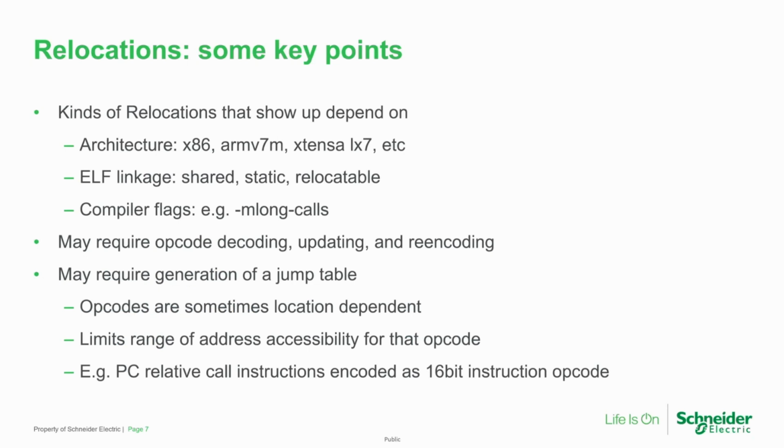So the key points of the relocation: LLEXT is very dependent on the architecture because, as I said, you have to parse the whole code. So if you are on x86, you have to know which are the x86 instruction codes to be able to patch them. Same for ARMv7, and same for Xtensa. I think today the work has been done on Zephyr for ARM, and that has been done for Xtensa as well. Not sure about the rest.